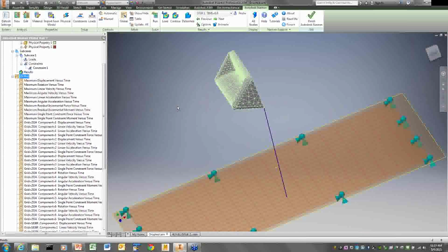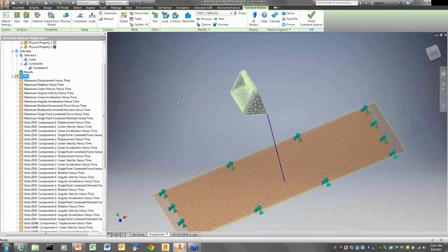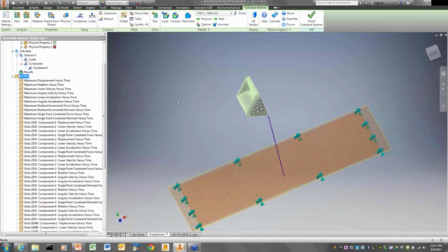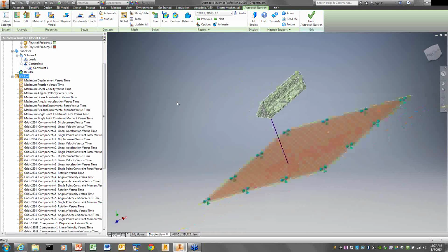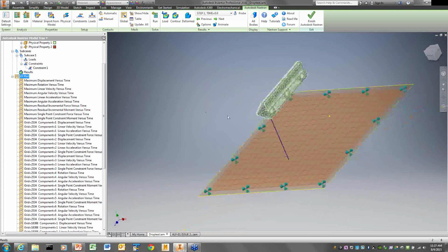and you'll be left with the low frequency noise. I used to do a lot of shock test work with ships. When you hit a ship with a shock wave, like from an underwater mine, you'll see a lot of high frequency noise as the panels of the ship go shaking around like crazy, and then they all damp out. What you're left with is the natural frequency of the whole ship vibrating, which is a much lower frequency and takes a lot longer to damp out. So yeah, an FFT, a fast Fourier transform, will show you all the natural frequencies of this structure that you would get if you happened to hit it with a hammer at that point. So it's a way to extract natural frequencies.